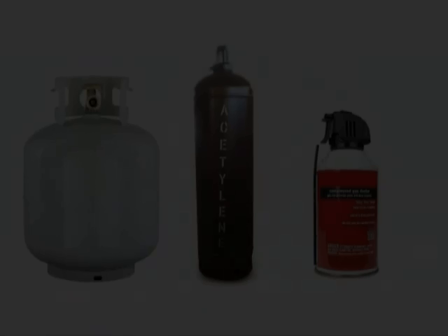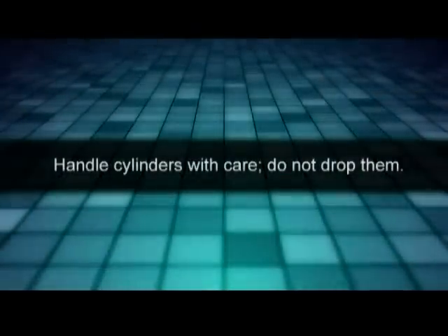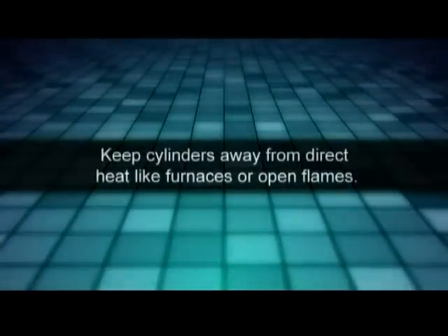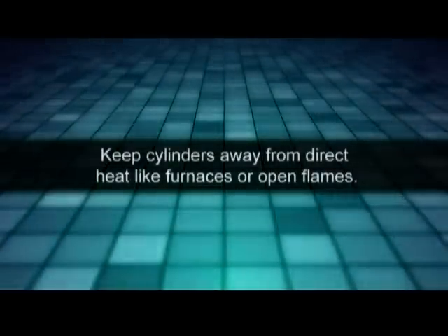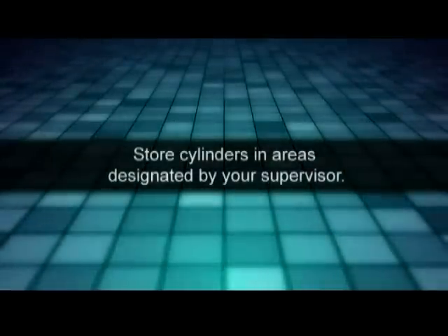As a precaution, you should handle cylinders with care. Do not drop them. Keep cylinders away from direct heat like furnaces or open flames. Store cylinders in areas designated by your supervisor.